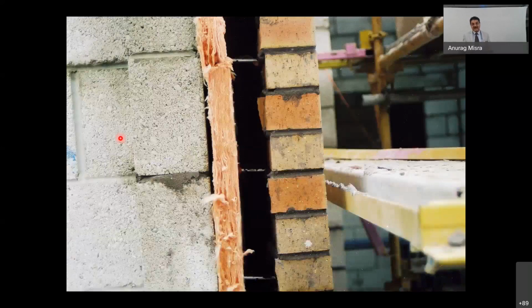Then comes insulation. When you are going for the pre-engineered structures, how are we? If we are going for only the steel buildings, then it won't be insulated. Even if you are providing boards, it won't be insulated. So that's a typical example of having double walled construction, where you have an insulating layer inside the two walls, and that gives you a good thermal insulation.